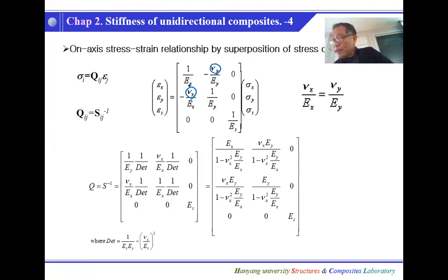So these are, of course, the X directional Young's modulus, the Y directional Young's modulus, and Poisson's ratio, and these are symmetric, so these have to be the same. And this is the Y stiffness and shear modulus. So how many independent stiffness values?